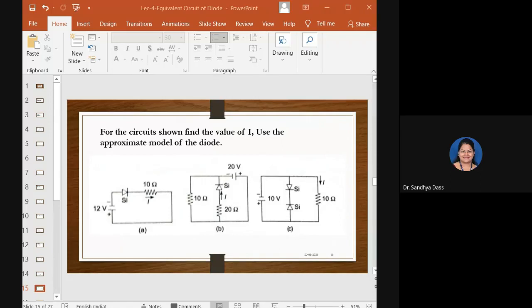The diode will not conduct. So the circuit is not complete. So there is no current flowing through the circuit. So how can you measure I there? How do you represent your answer there? Since the diode is reverse biased, the current I will be 0, isn't it?